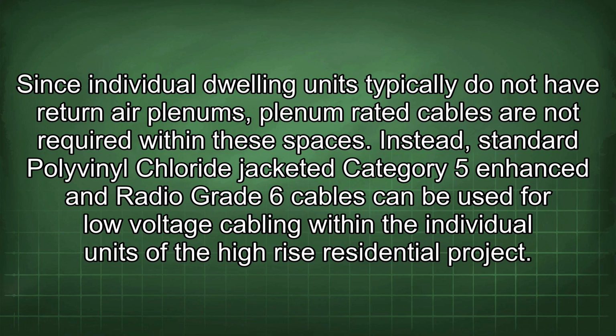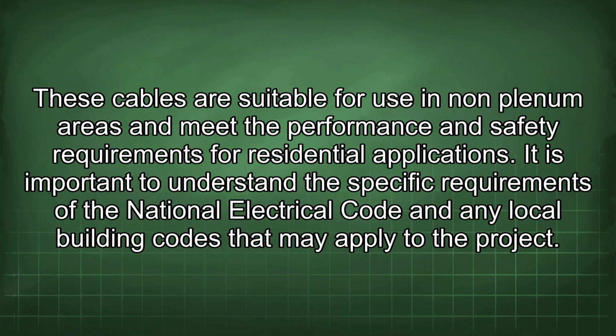these spaces. Instead, standard polyvinyl chloride jacketed Category 5 enhanced and Category 6 cables can be used for low voltage cabling within the individual units of the high-rise residential project. These cables are suitable for use in non-plenum areas and meet the performance and safety requirements for residential applications.